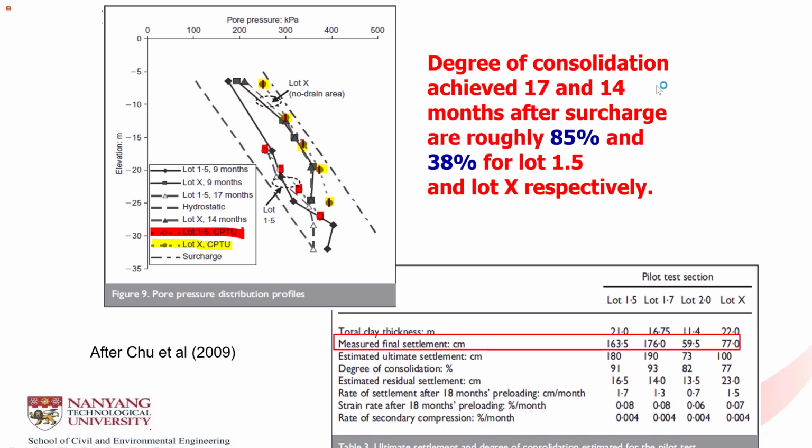By the way, we actually verified the pore pressure for the comparison lot X, because one of the arguments is whether the pore pressure measurements are indeed reliable. So what we did is we put the CPT in somewhere close to the piezometers for lot X, and we did a CPT holding test to measure the pore pressure, and then we compared with the piezometers.